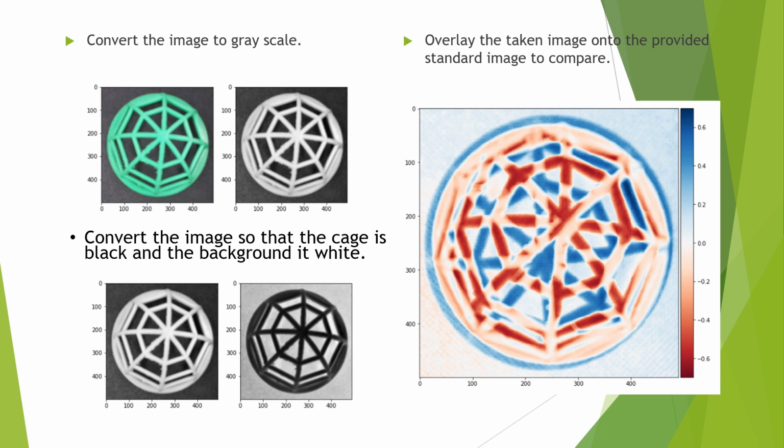And this kind of shows that if you have a standard of what a good part should look like as is being 3D printed, and then as you're doing any new parts, you're comparing that against that standard image to see if you have any shifts from the current part to the standard.